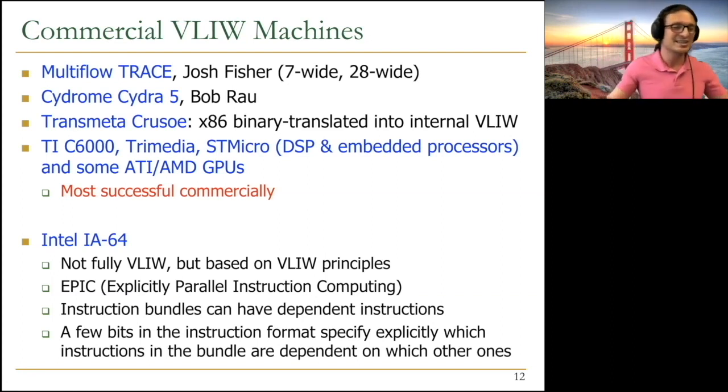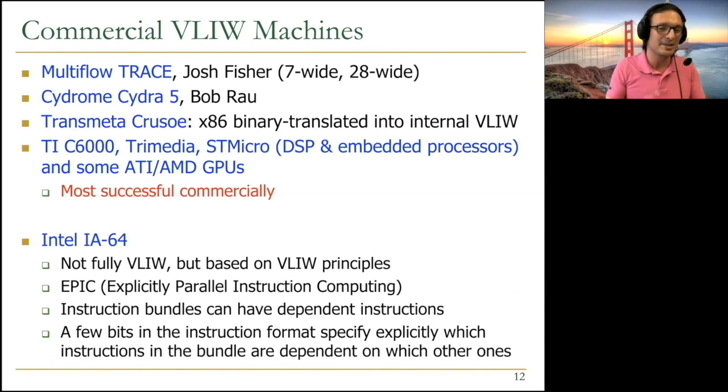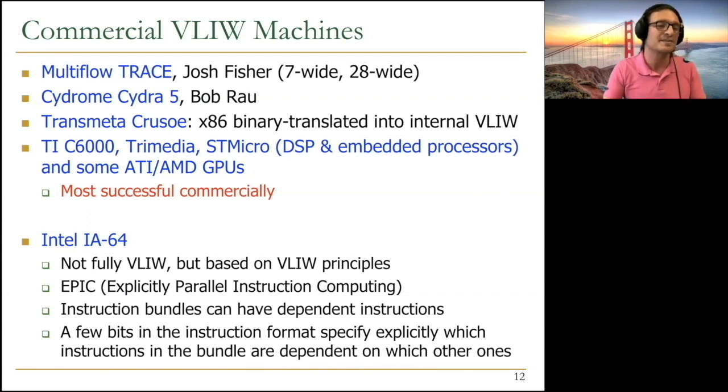If the instructions are committed concurrently, there are no problems if there are no exceptions. But if there are exceptions, you need to handle them in a manner. And VLIW architecture specifies exception handling also. So you need to look at the ISA manual in terms of how the exceptions and interrupts should be handled in a VLIW machine. So that's a very good question.